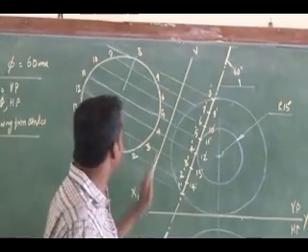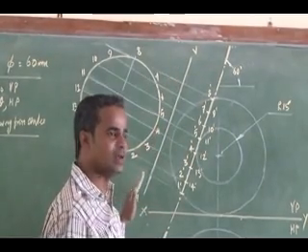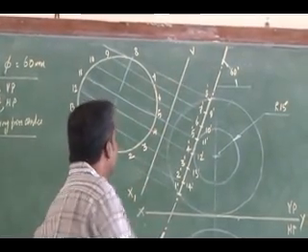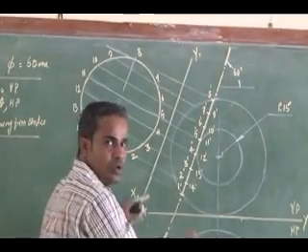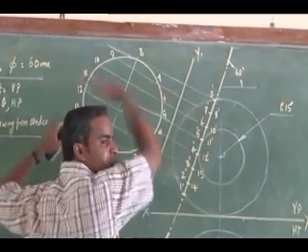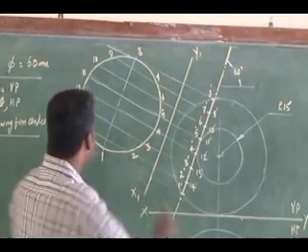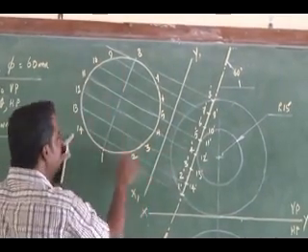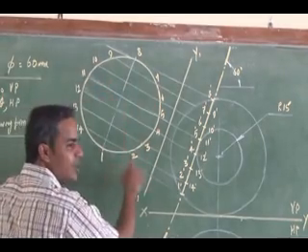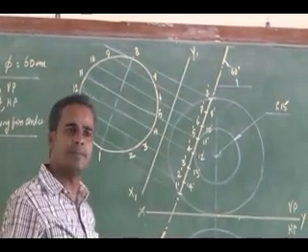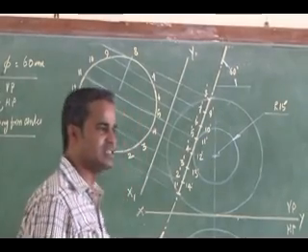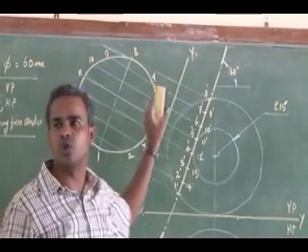So for that true shape, parallel to the reference line, new reference line, perpendicular to the new reference line, I have extended the projector from the cutting points I have marked. Right? Then in the true shape, that projector will intersect. So that location in an order I can give the cutting point locations. Right? So this is how the true shape is over.